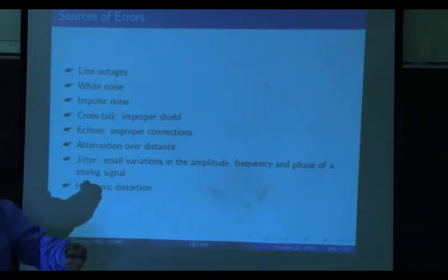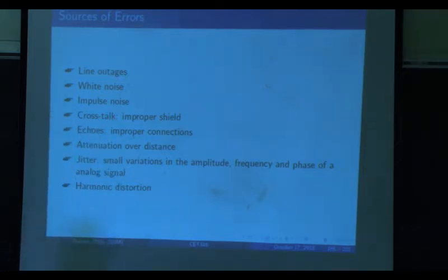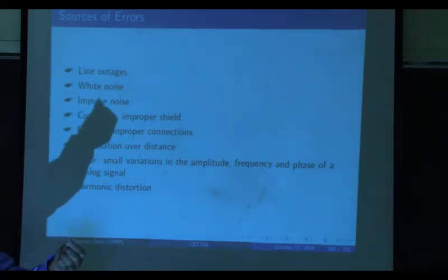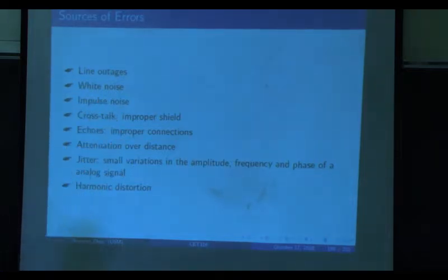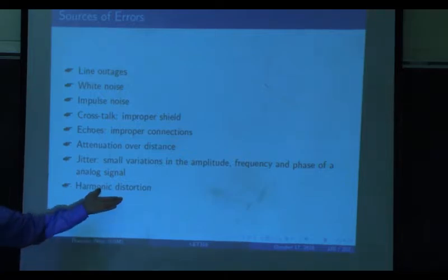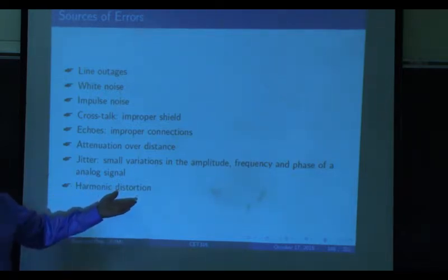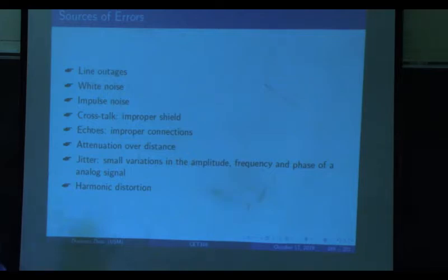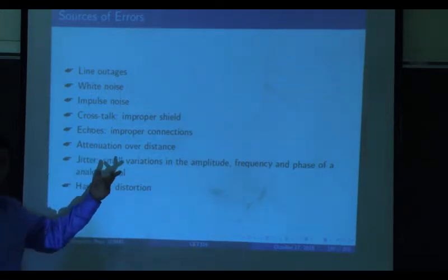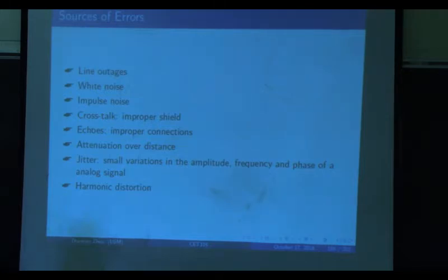Amplifier. We said a linear amplifier, but the reason is we have transistors inside. A transistor has a diode inside, so anything involving diodes or transistors must be nonlinear. So if you have devices like that inside, then this is a nonlinear system, and you are going to have harmonic distortion. For example, if this frequency equals 60 hertz, then you are going to have 120, 180. All these are called harmonic noise or harmonic distortions.